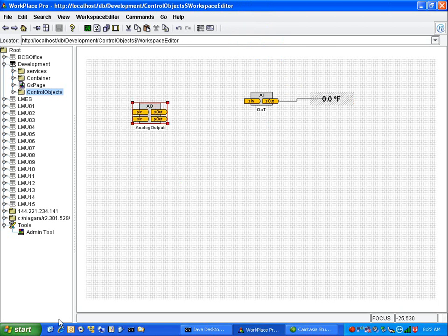An analog output is more of a command type object. Graphically, what this object does is give you right-click capability on a graphic screen where you can set a value. This is the type of object we use to simply have adjustable space set points, mixed air set points, discharge air set points, time intervals, any type of value you can possibly think of that you may need to have the customer right click and adjust will come through an AO type object.